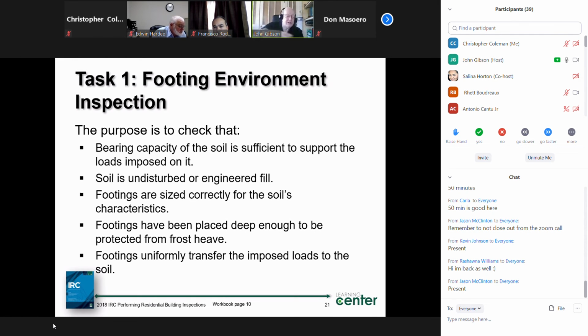From that point, I go to the floor above the floor in question. So the floor in question was the basement. So I'm going to the first floor above that. And that distance from that floor level to where this grade plane is, if it is 6 feet or more, then that lower floor is considered a story above grade plane. And I'd have to count it. Remember, we're limited to 3. So if I had 3 stories plus that basement, which now counted as a story above grade plane, I've got a 4-story above grade plane structure.